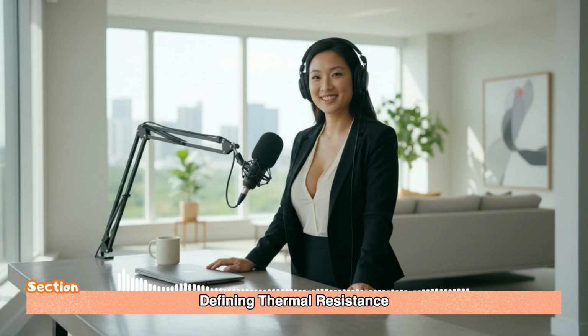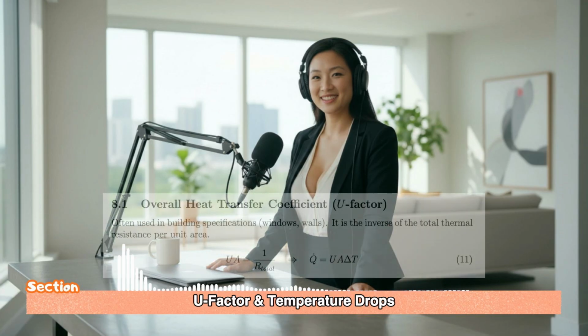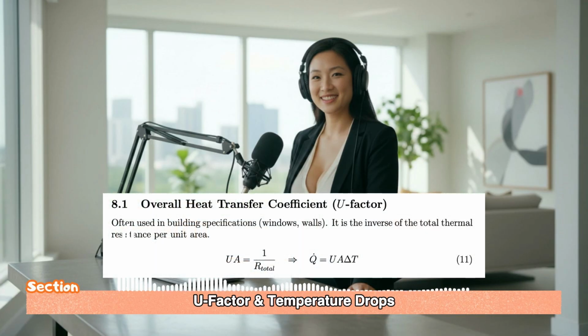It's incredibly flexible. Before we get to the big window example, let's connect this to a term people might see in building codes or on product labels, the overall heat transfer coefficient, or U. This is purely a convenience metric. Engineers often like to write the heat transfer equation as Q dot equals U times A times delta T. If we compare that to our series resistance equation, Q dot equals delta T over R total. Well, the relationship becomes perfectly clear.